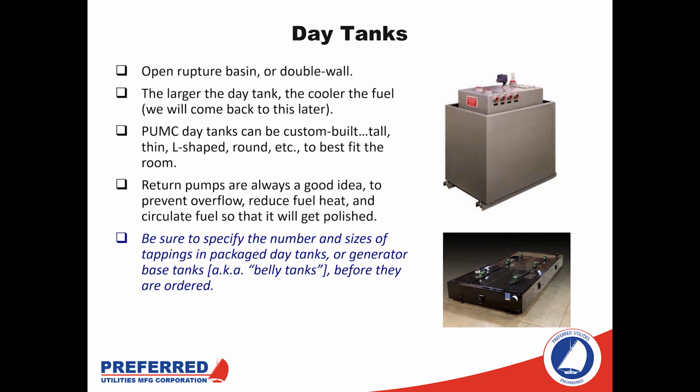And we want to make sure with the day tank that we're specifying the number and sizes of the connections. So it's very important that we have these connections on there. Some day tanks will have a proprietary connection or won't have something standard like an NPT fitting. It's important to understand that if these don't have a standard connection, the tank itself may last for a very long time, but the electronics that are hooked up to it, not as long. So we need to keep in mind that for future retrofit, it may be important to have a standardized connection on there.